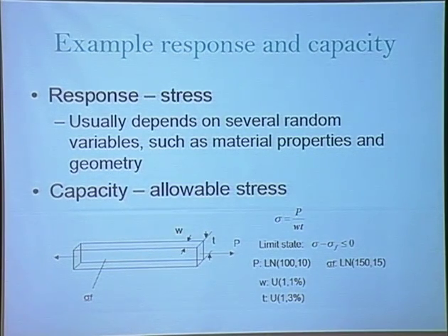A normally distributed variable can go from -infinity to +infinity, and it's clear that if the dimensions are going to be grossly inaccurate, somebody will catch it. So even if you don't have strict quality control, you can count on the distribution being truncated. If you do have quality control, then there is somebody on the assembly line whose job it is to make sure that you build it to specification within a certain tolerance. It may be somebody at Boeing or at Ford or somebody at the FAA, and that truncates the distribution further.